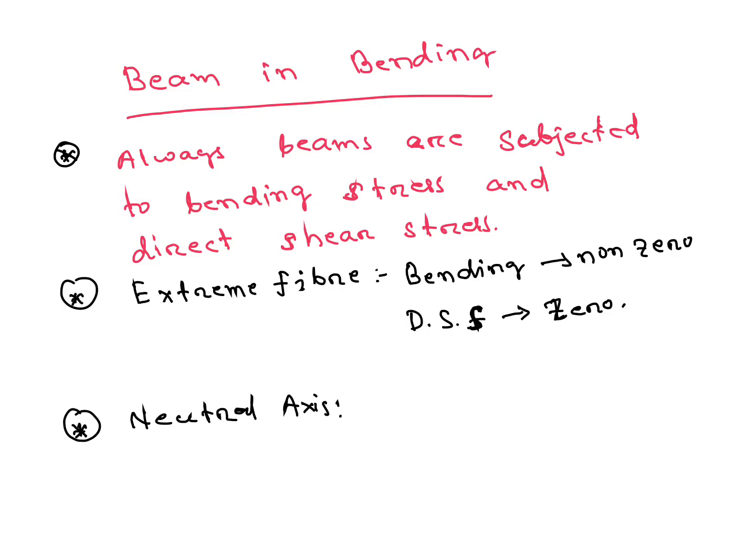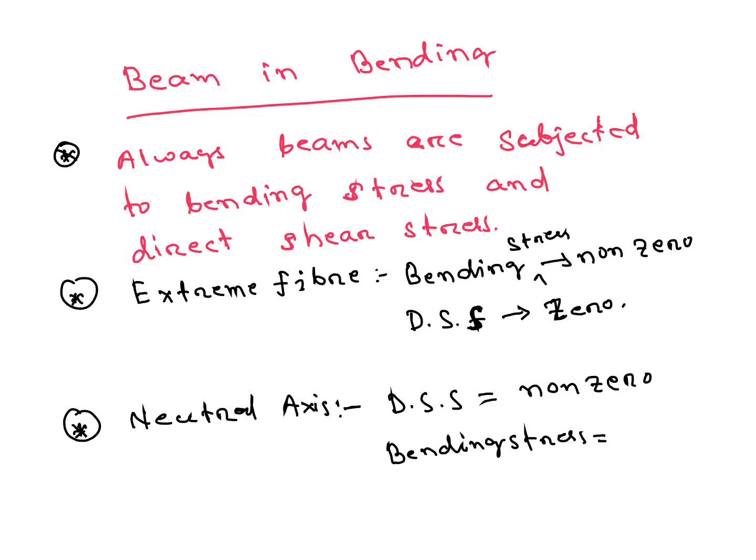And at the neutral axis, direct shear stress is non-zero and bending stress is 0. So you have to remember both the extreme fiber and the neutral axis. Many times asked in IES exams.